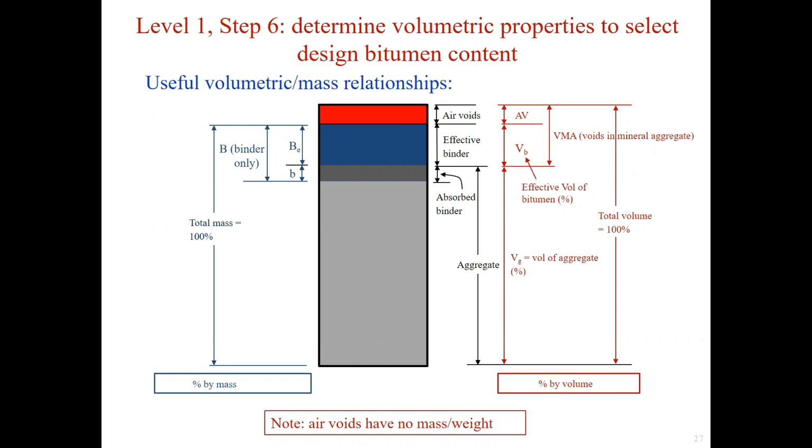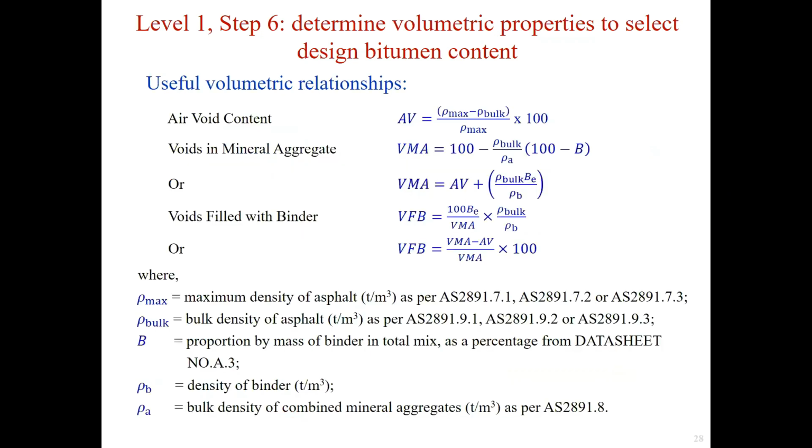I would strongly suggest you to pay more attention to these definitions and relationships, as you'll need to use them for some calculations. So based on previous figure, we have the following useful volumetric relationships for air void content AV, voids in mineral aggregate VMA, and voids filled with binder VFB.